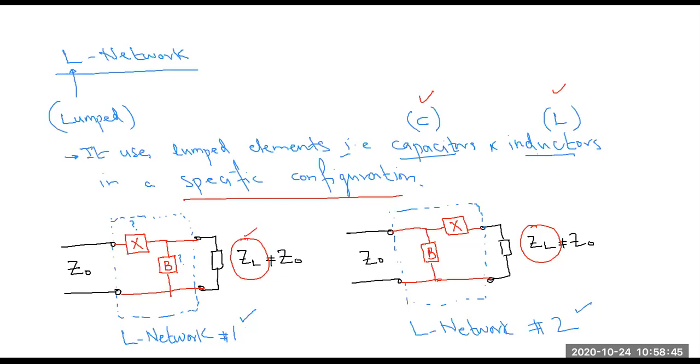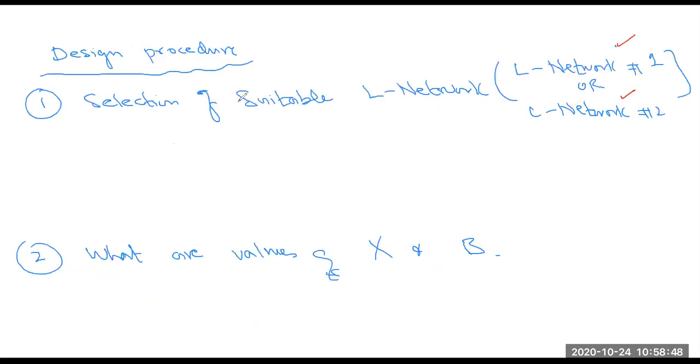As we are using the Smith chart, I'm only talking about the Smith chart solution method. So how will you answer this question with the help of the Smith chart? Now, whenever you use the Smith chart, we only talk in terms of normalized values. So the first thing you will do is to normalize your load.